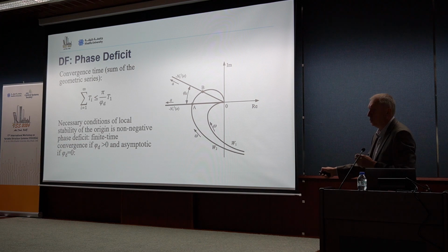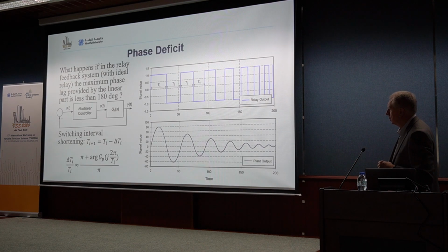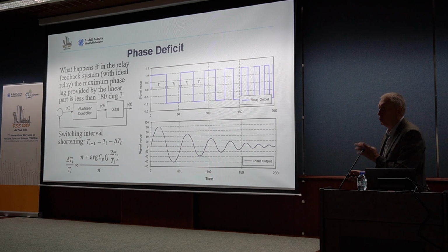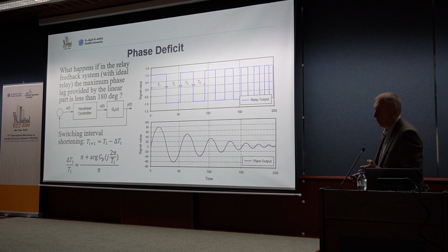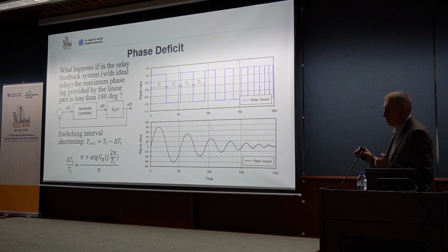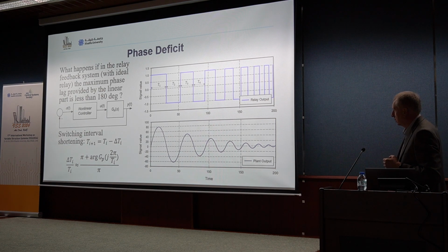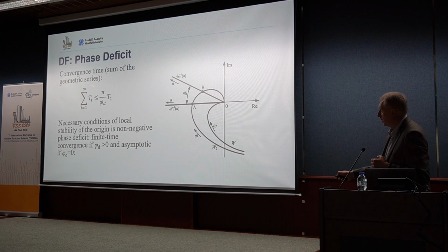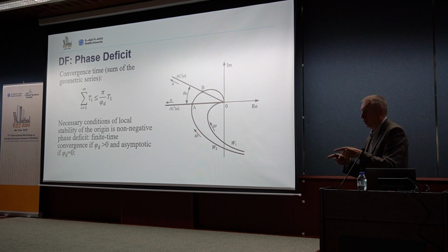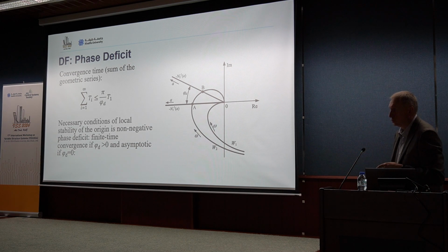I put smaller than or equal to, assuming a not constant value of the phase lag here, but depending on the frequency, but with high frequency the phase lag becomes high and reaches the maximum value at infinite frequency. So it's under that assumption. So that brings here this smaller than or equal to sign.